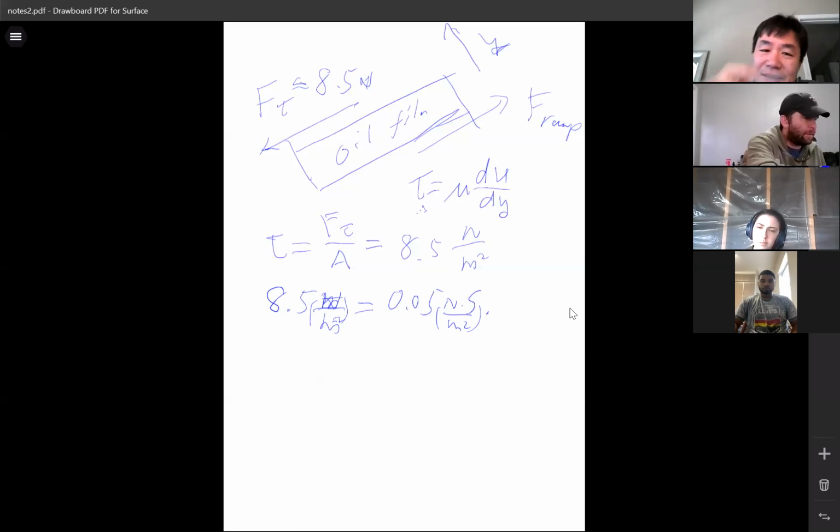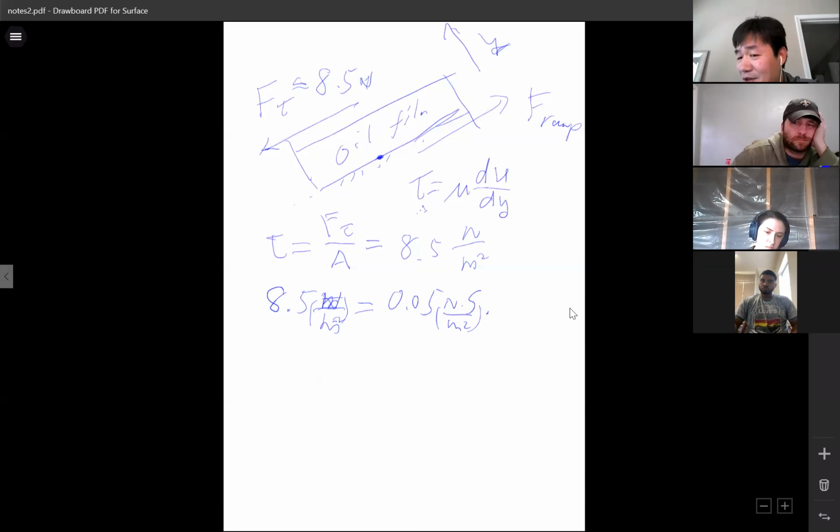Yeah, it's gonna be more fluid at the top, and then slowly. Exactly. More fluid at the top because at the bottom it's connected to the ramp. Okay, we mentioned last time the non-slip boundary condition. Remember, I'll give you an example: flow over a plate. At the bottom, when you connect to the board, to the surface, you have 0 velocity. It's called the non-slip boundary condition. It's always like that. Exactly on the surface, there's no velocity, 0 velocity. Do you agree? Basically, it follows the surface.